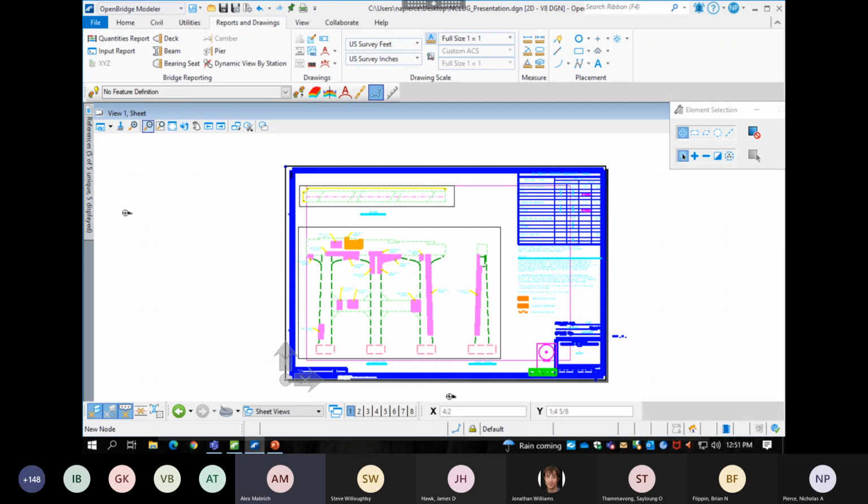At this time, we can transfer some reinforcement. Actually, if you're designing in LEAP Bridge Concrete, the column and the footing standard, you can send the reinforcement back to OBM and it will show as raw concrete elements, right? That's one-way interaction. However, if you change the design, it's not going to change the OBM model.